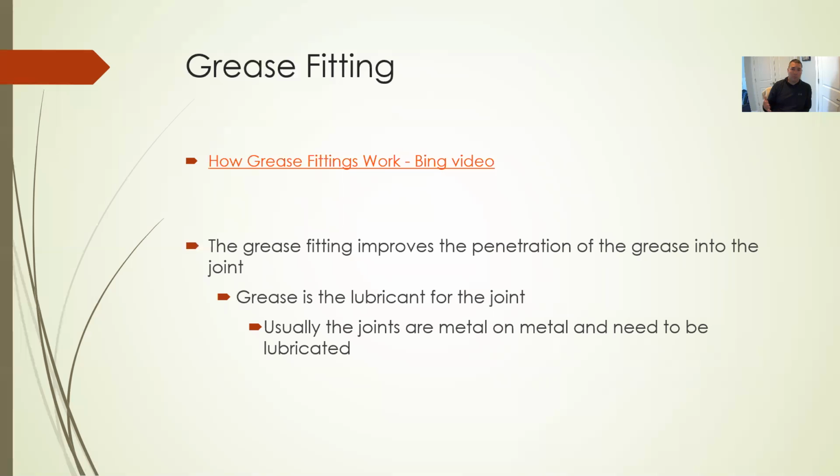So this thing just sits there for 8 months. You still need to go through it, do the preventative maintenance things, in order to make sure that the oil is up to date, its viscosity is right, so that way when you start running that piece of equipment, it is in good condition.